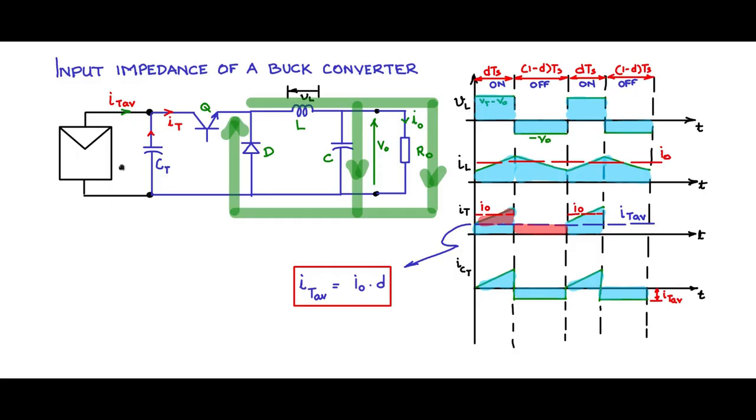So this placement of the capacitance here is very important in the case of the buck converter. In the case of the boost converter, this problem did not arise because the inductance was on the input side and there was a continuous current flowing through the inductor. However, one can put a capacitance at the terminals of the PV module. It will improve the ripple, and it will make the input voltage much more stable. It will stabilize the voltage. However, it is not mandatory for the boost converter, but for the buck converter, placing the capacitance is mandatory, is compulsory.